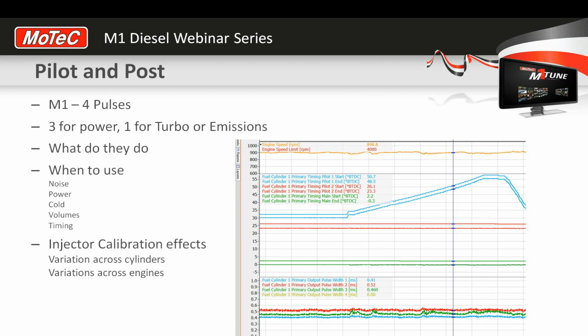Now, one of the ways to help if you've started tuning your diesel and you're struggling with getting pilots to stay working, the first global overall rule with pilots is to keep them separated so they don't run into one another. You configure that in the timing worksheet, I believe you'll find. I think it's the pilot one, or if not the main one, you'll see a worksheet configured with a screen similar to this.